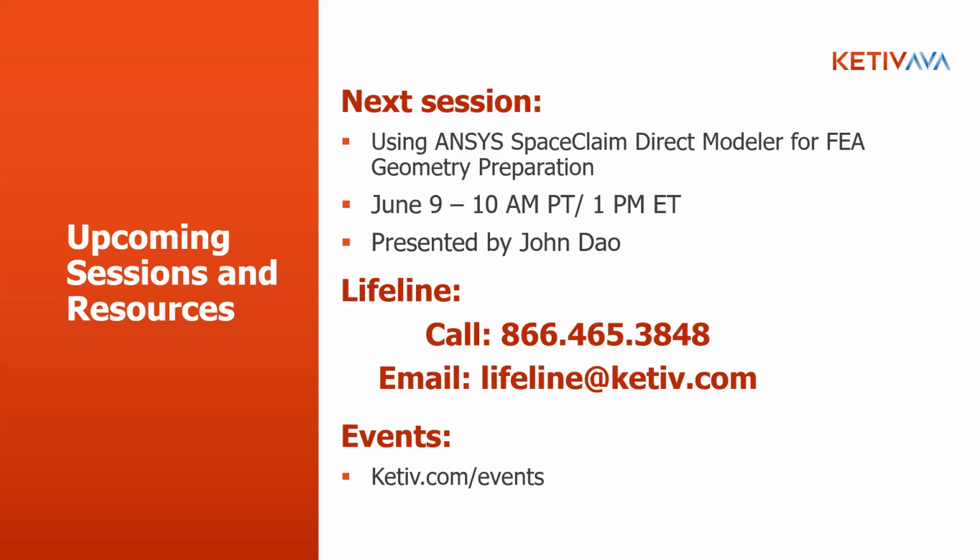And someone asked about how SpaceClaim's advantages compare over Design Modeler. So SpaceClaim has these additional features that will help you prep your model for analysis better than Design Modeler itself, right? So for example, I was easily able to extract the flow volume by just clicking on two keys.